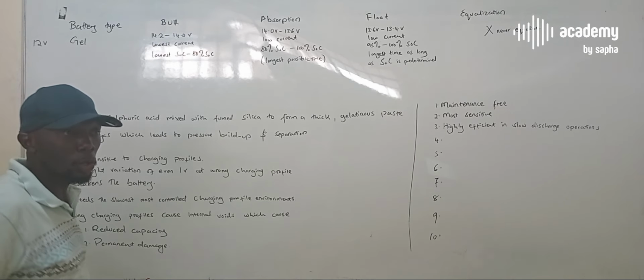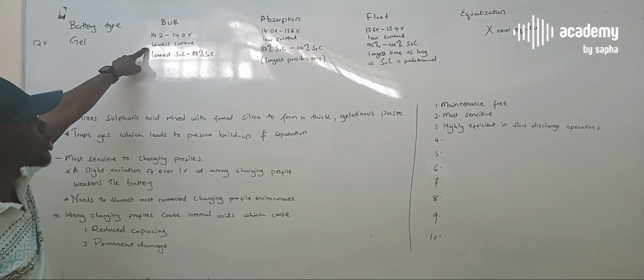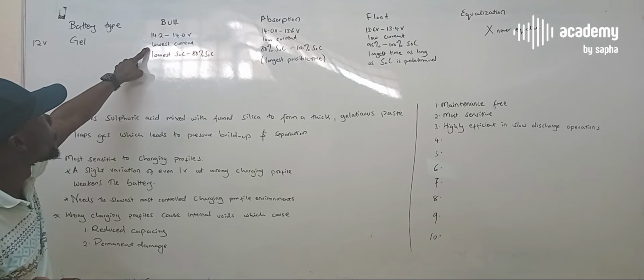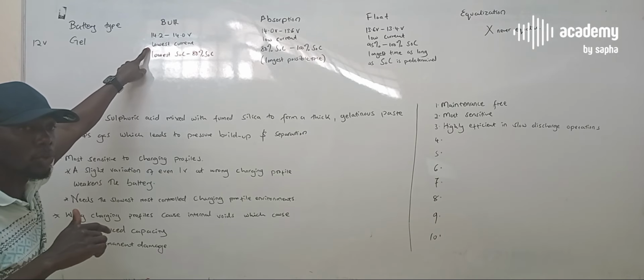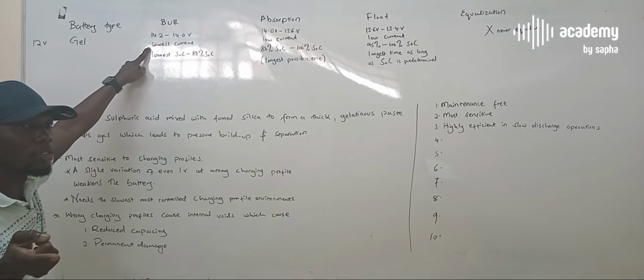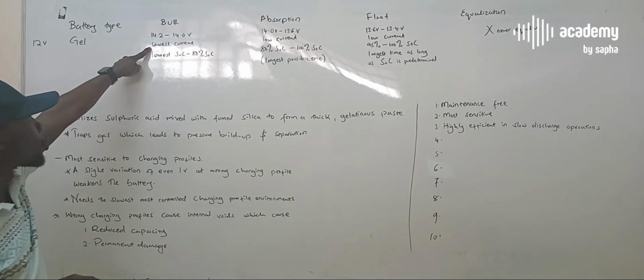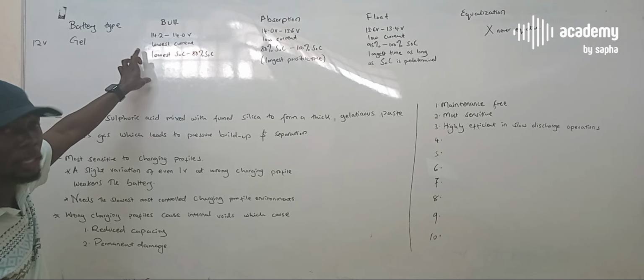And you use the lowest charging current. Actually, this charging current should be, I think some manufacturers cap it at not even half, at a quarter of the C rate. Some of the specifications that I have, we will look at them independently, but some are saying you cap it at a quarter of the C rate.